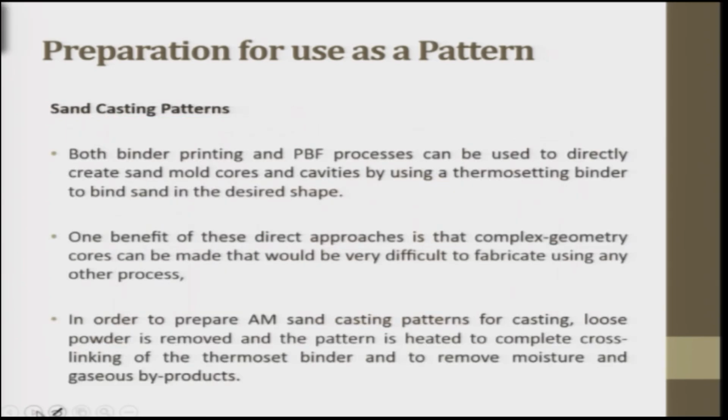Next is the sand casting patterns. Both binder printing and powder bed fusion processes can be used to directly create sand mold cores and cavities by using thermosetting binder to bind sand in the desired shape. One benefit of these direct approaches is that complex geometry cores can be made that would be very difficult to fabricate using any other process.